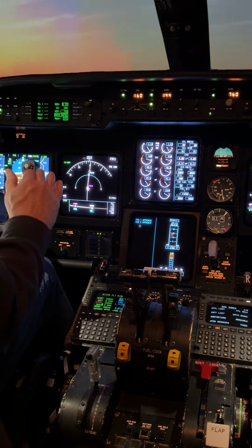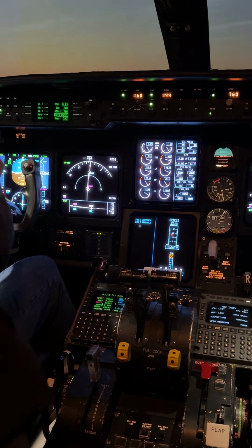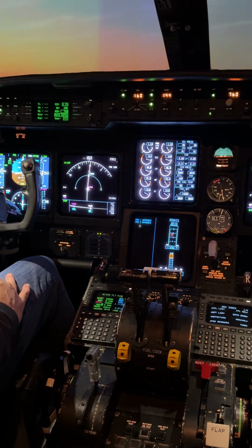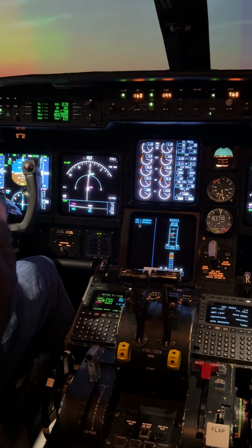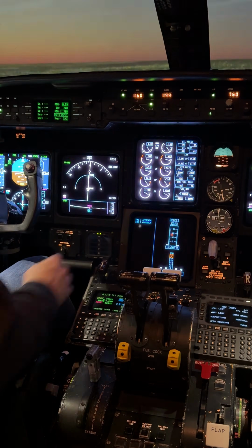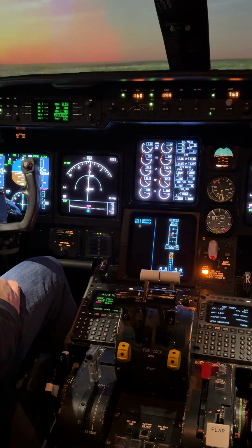Now, once we get to 2,000 feet, this 2,000 is going to go away. And the only thing that's going to be left is going to be our minimum of 760 because there are no other step-down altitudes. MDA is the next thing and the last thing. There we are. Continuing down, this goes away, which means we're on our way down to 760. We're in VNAV. It's working great.